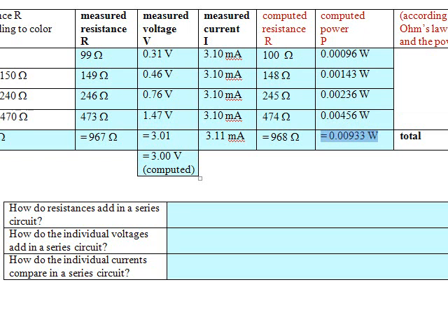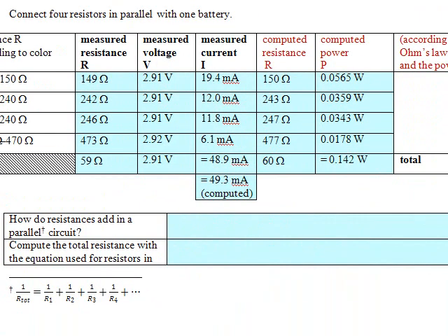In fact, in a parallel circuit, you get the total power to everything you put in the circuit, all the appliances, in this case all the resistors. In series, you get only a little bit of the power to them. The total current is relatively small, as we can see, and they all have to share the voltage, while here they all have the nominal voltage from the battery.